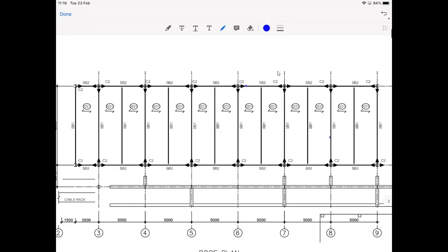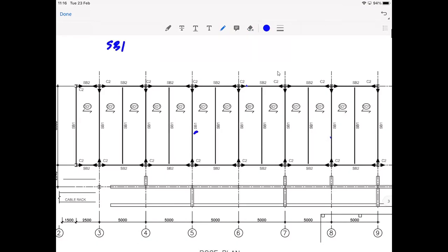So you must provide some means to hook up the floor system with the beam, even though you may not plan to design the beam as a composite structure, which I think if you know how, you should always. So anyway, as a result, SB1 is fully braced by the floor. So you can go ahead and design the SB1 right away.